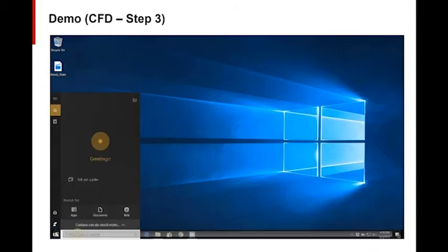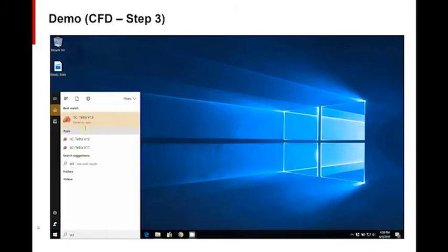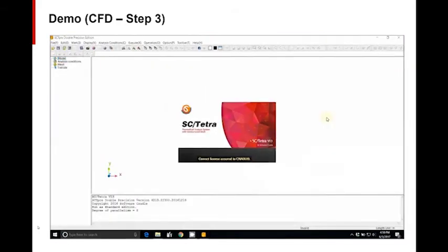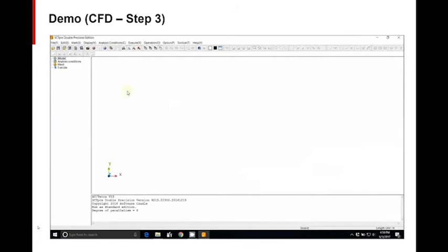The second step is we set the time step for the simulation. And for this case, we calculate that we need to simulate about 0.1 seconds. So using a time step of 5 microseconds, we need to simulate 20,000 time steps.